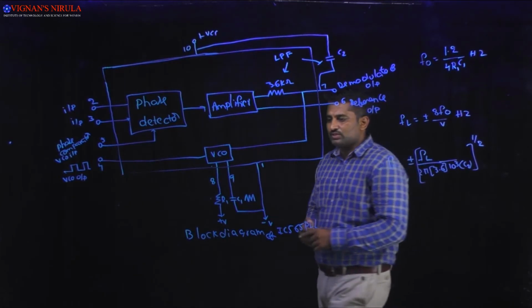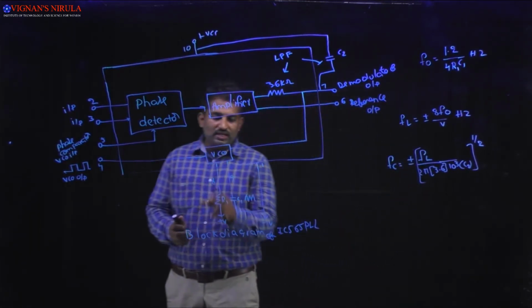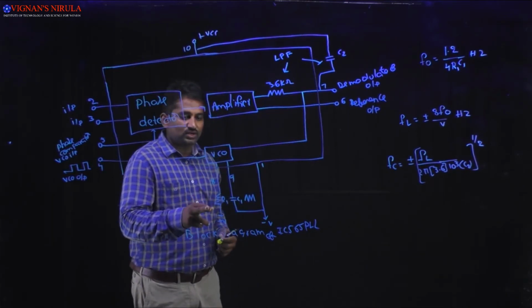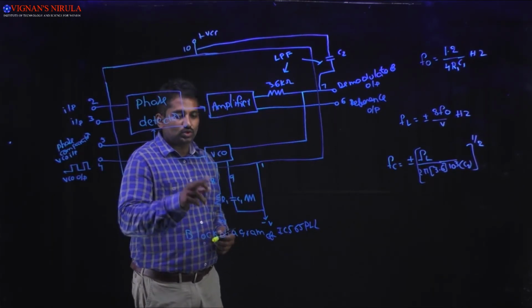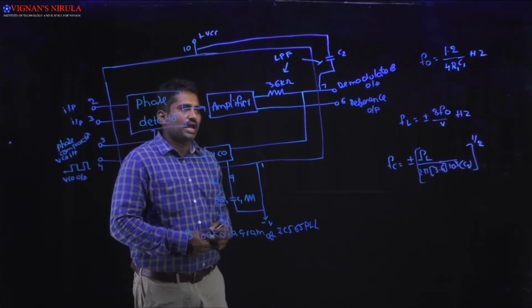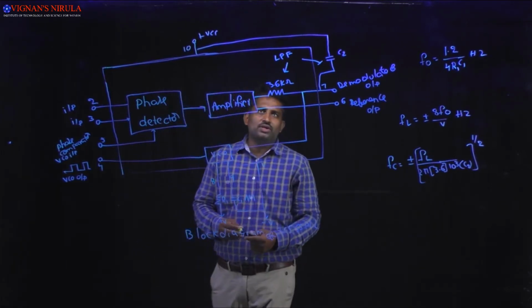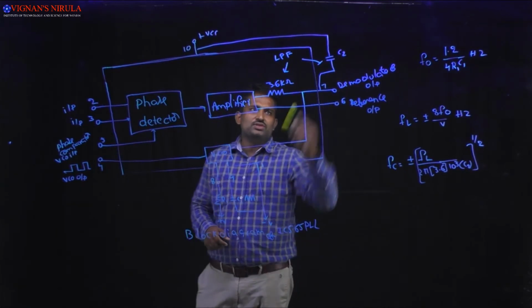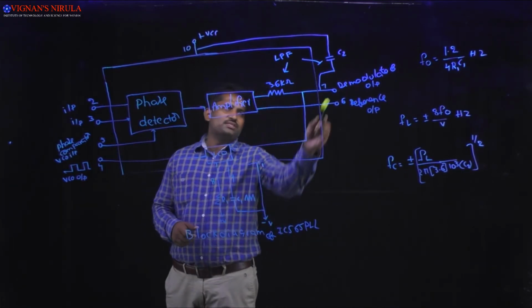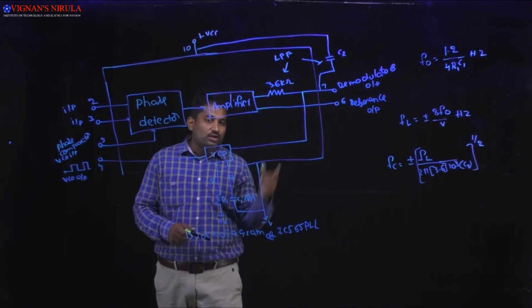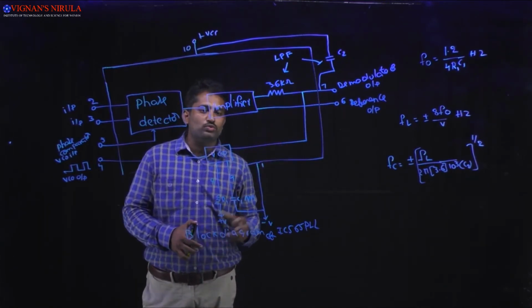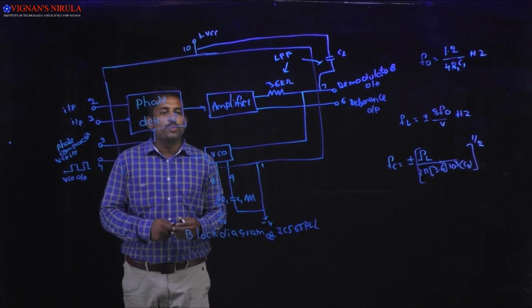And coming to pin number 8 and 9, here we are connecting the resistor R1 and capacitor C1 to pin number 8 and 9. And here we are connecting a capacitor C2 in between the pins 7 and 10 across the resistance 3.6 kilo ohms to form the low pass filter.